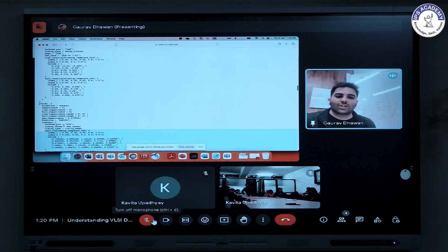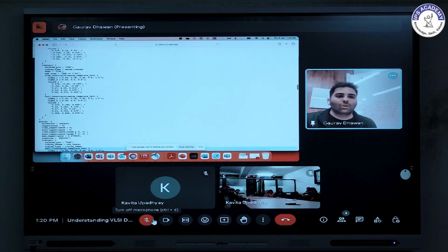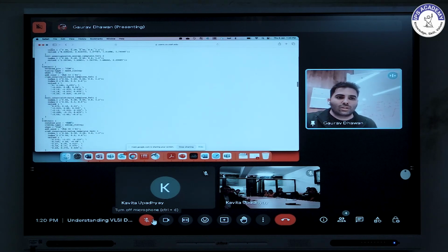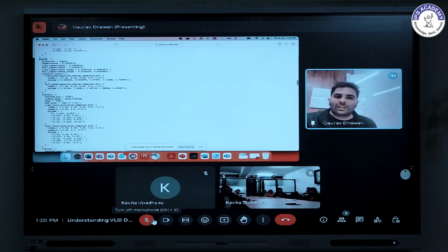This is just for the timing arc. We also capture details about setup, whether setup rising, when your output is rising, what is the setup time. The related pin is clock, under the D pin if you see here. So your pin is D, your related pin is clock, and this is your hold rising, meaning what is the hold value.